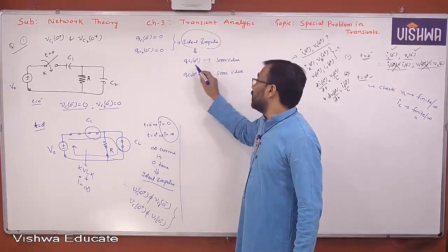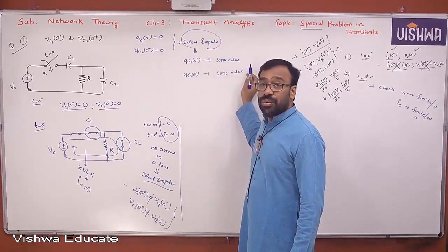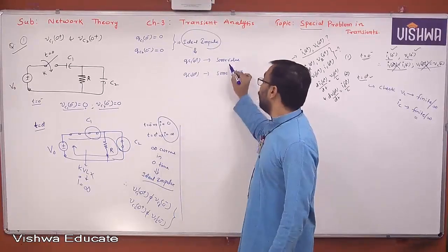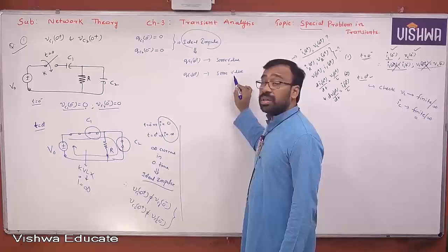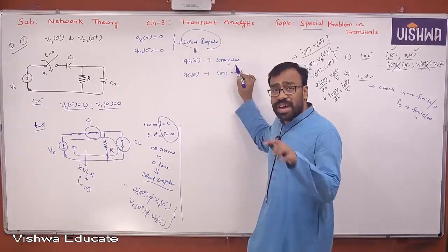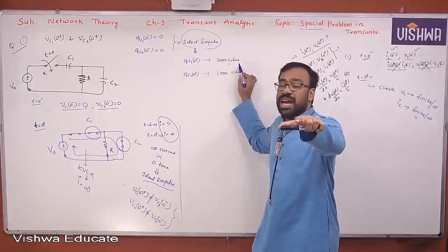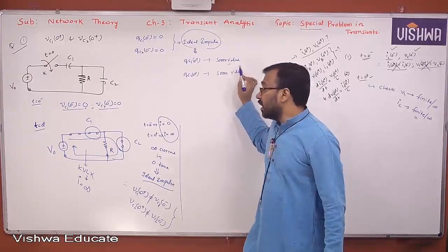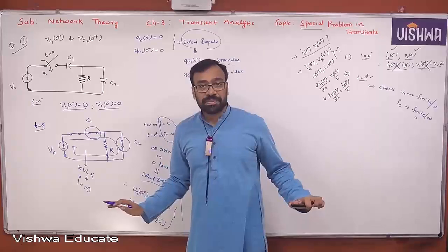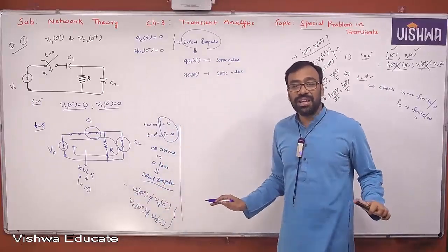When the charge changes to some other value, the voltage will also change. But which value will it change to? This ideal impulse will force the charge to change to some value in such a way that Kirchhoff's voltage law is satisfied. You understand, all of you?